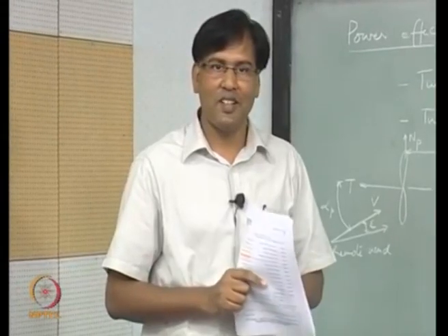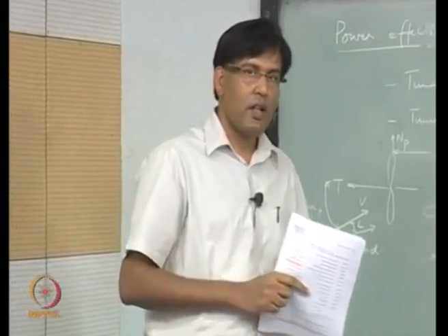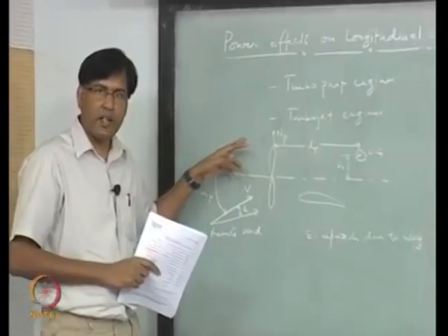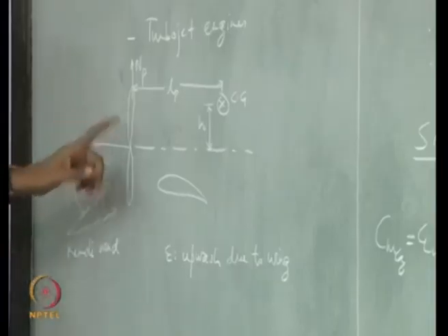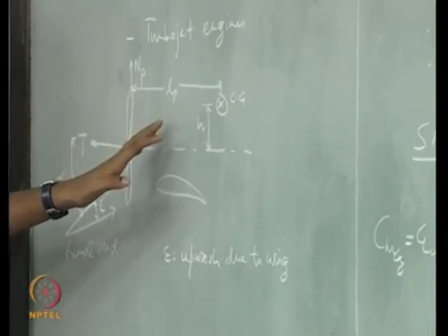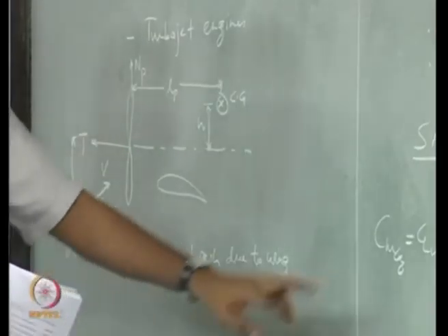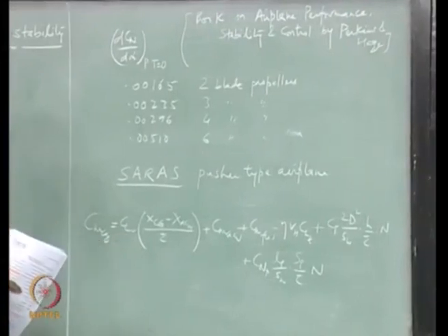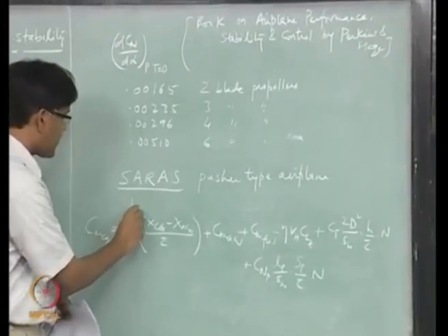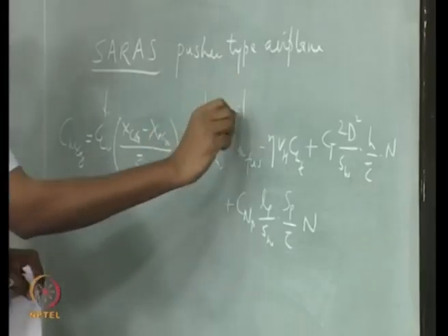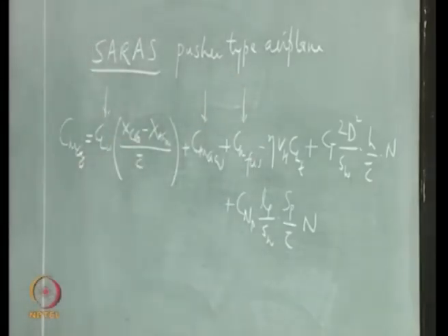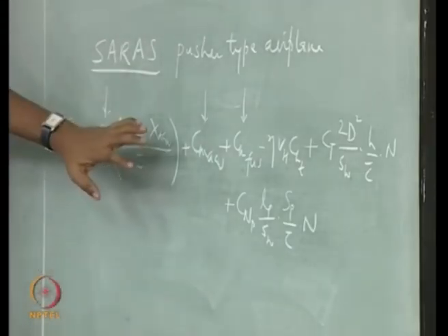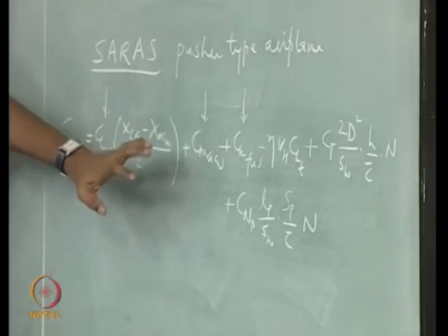Does this give a significant contribution to the lift of the aircraft? This will have an effect on the lift, but not significant, because the wing is lying behind this. So the slipstream is going to have an effect on the lift coming from the wing. All of these effects are going to be there, but they are not so significant. They are very small contributions.